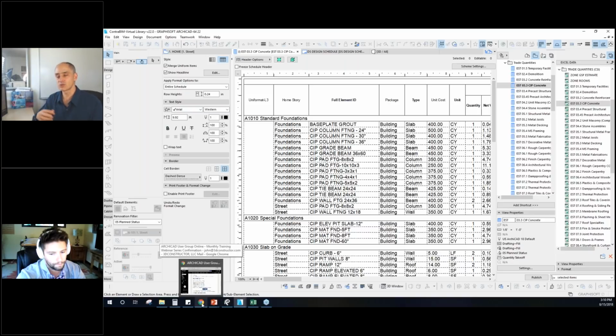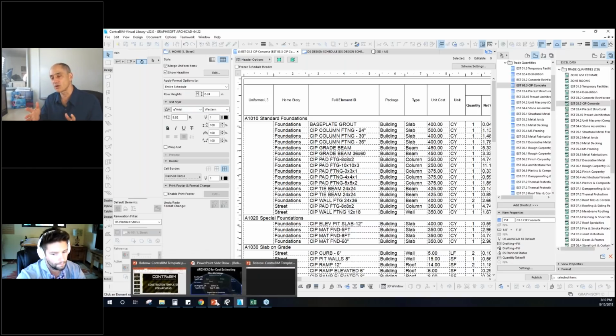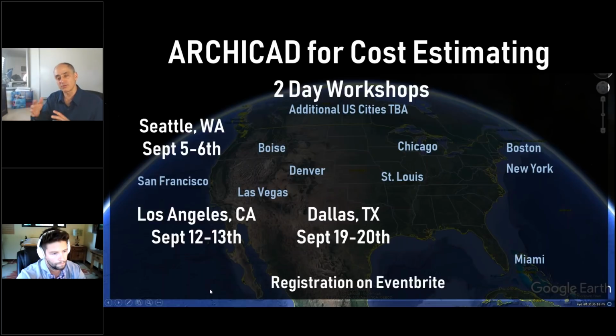Revit has some advantages in terms of things moving with each other, or you can say this is attached to that, and when I move this, it changes. Sometimes that can bite you because things can lock up because there's conflicting changes, or you make one change and it affects other things inadvertently. With ARCHICAD, I would say you have more control over what things you want to link and what you don't. But those are just some thoughts that may or may not be clear. I think having a Mac version is a big advantage for many of us.